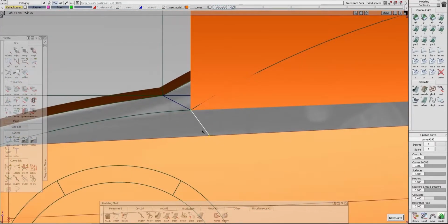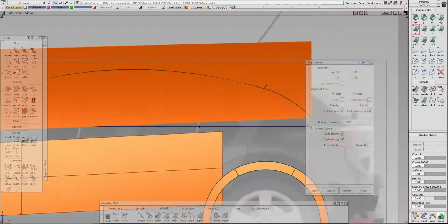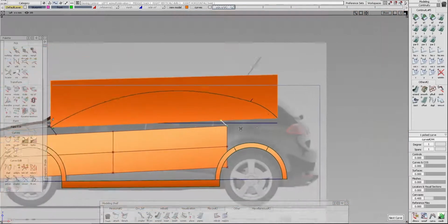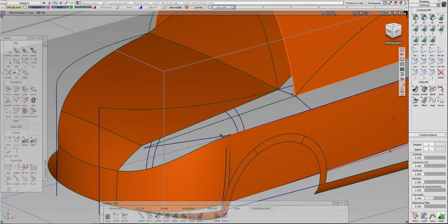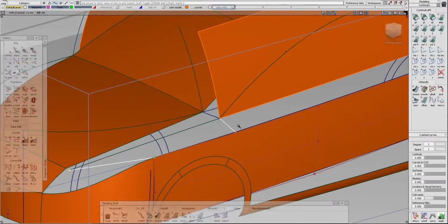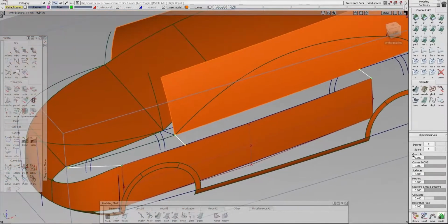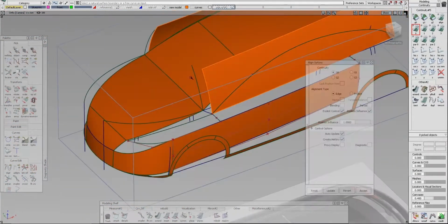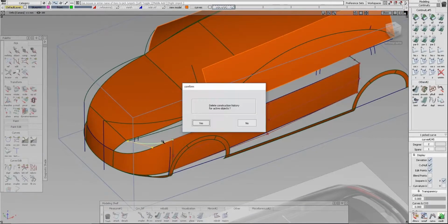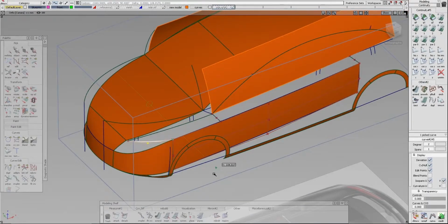So this will be the generation curve for the shoulder of a car, and also here for the headlight. So again, I turn CVs on, and I'm aligning this one with tangency, but now I'm moving that middle point in Y, so I didn't keep that tangency.